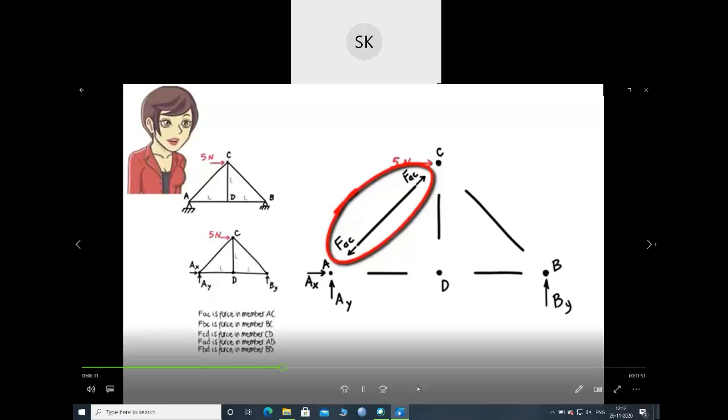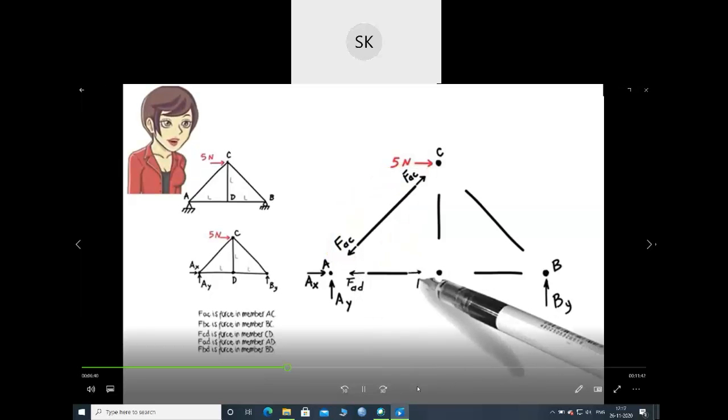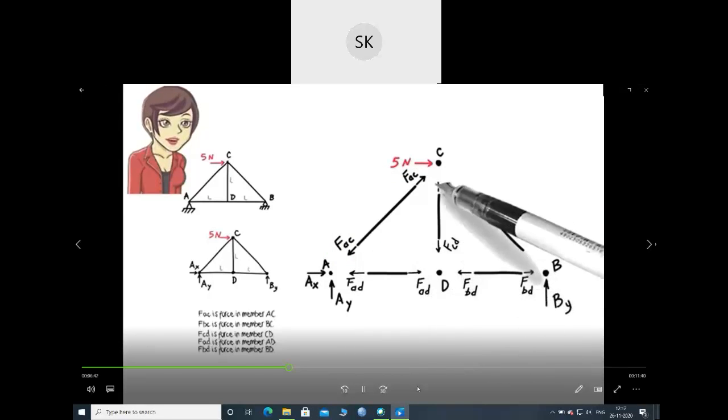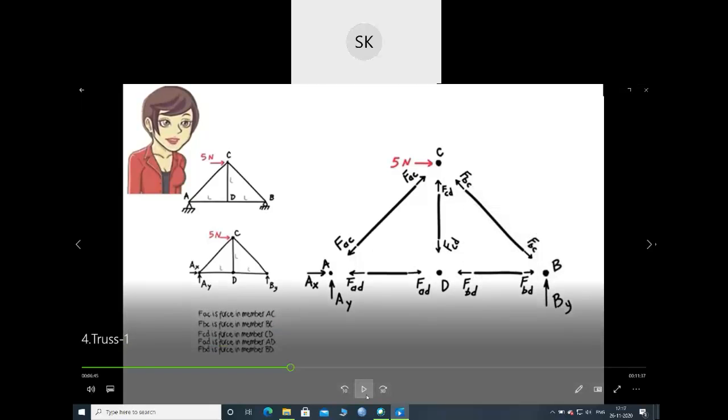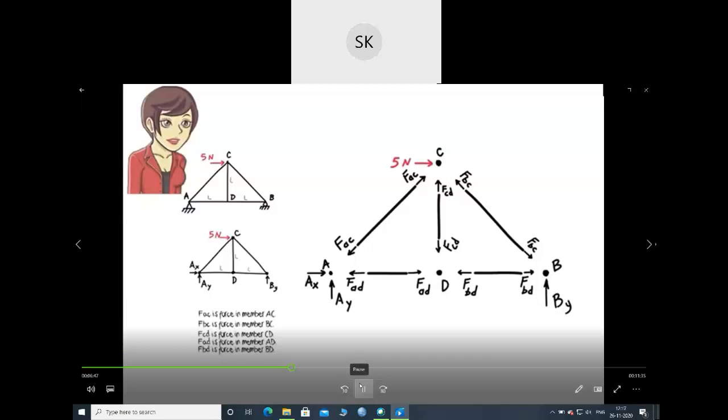The only force present in the diagram is the unknown tensile axial force in the member labeled FAC. I am going to draw the free body diagram for the other member segments in a similar manner. So in this problem, we have assumed that all the members are in tension. Okay, let's see if our assumption is correct or not. That's why the direction of the member is in this way. Each member is assumed to carry an unknown force. The member is assumed to be in tension.